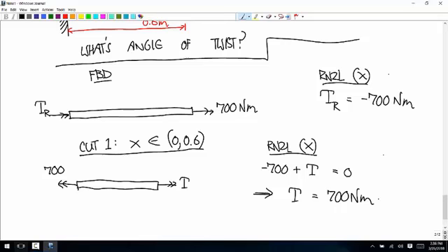You don't have to go through all that if you can just look at that and see it, and if you can't now, you will by the time you do a few of these problems. But in more complicated problems, remember that you always can just go back to calculating the external loads, do the cuts, calculate the internal loads, and those internal loads are what we're looking for.